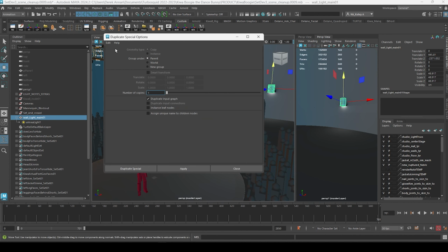I did forget to pick a material for my lights. So what I'm going to do is do a wildcard selection of all their geometries. So I'm going to select this and paste it here where I'm going to select by name, but I'll put a star in place of the number. And that should select all of them. And I'm going to right click, assign new material, and assign an AI standard surface shader to them. Call this aiAtmosphereVolume wall light matte, and bring it down.